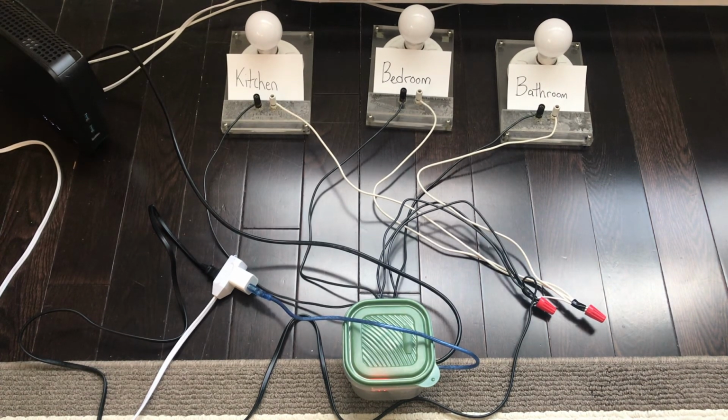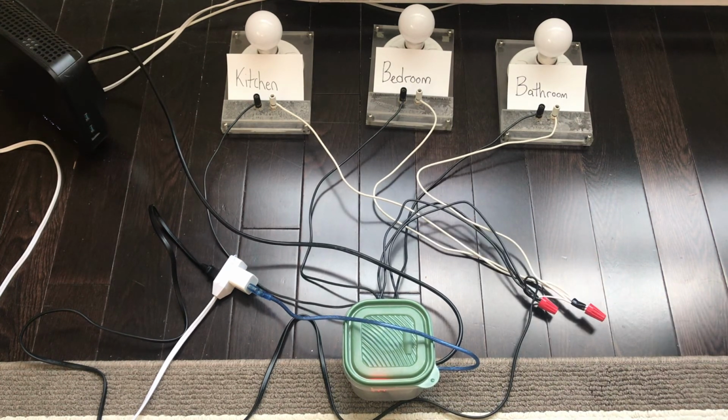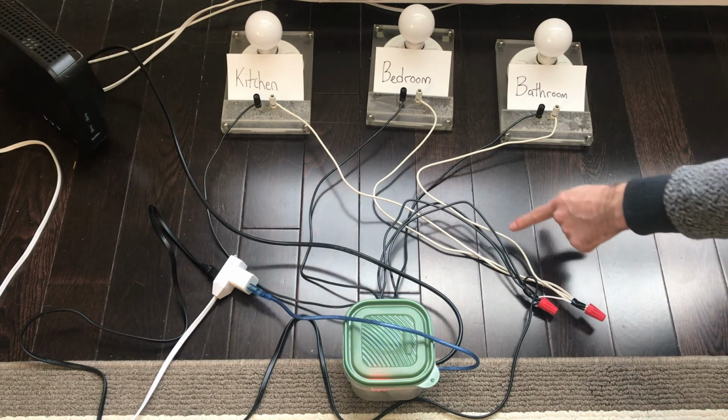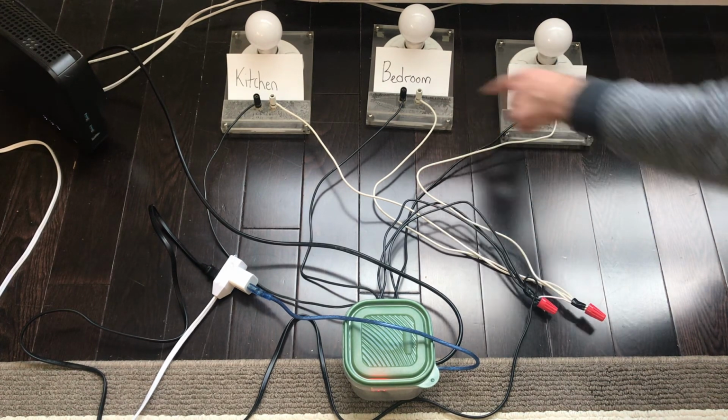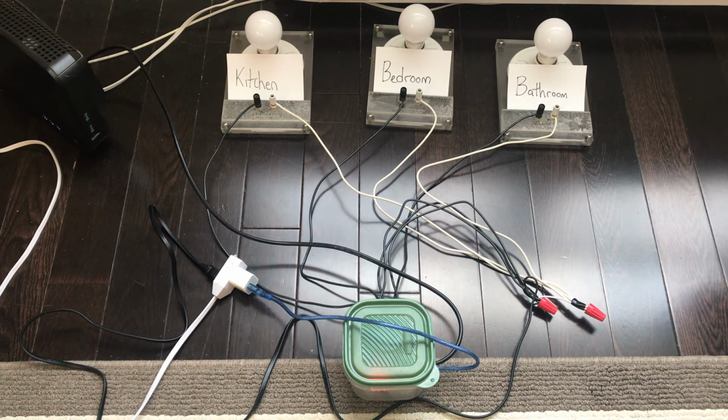These two wires were split into three separate wires respectively, using 14-2 gauge wire and marrettes, as we can see here on the floor. The three neutral wires ran directly to the lights, while the three hot wires ran into the common terminal of the relay board. This created a three-line parallel circuit where the power source was a 120 volt AC wall socket, and a respective light and relay occupied each line of the circuit. It was necessary to use 120 volt light bulbs to handle the voltage.